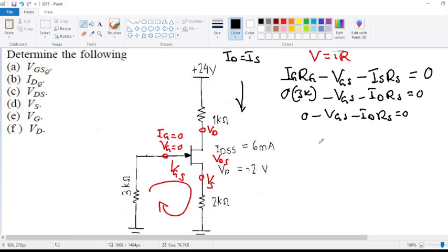So we are going to have our VGS. Let's take the VGS the other side. So we are going to have VGS is equals to negative ID RS. Now for us to remain with our ID here, we are going to divide throughout by what? Negative RS, also here by negative RS. So meaning the negative and negative disappears, RS and RS goes.